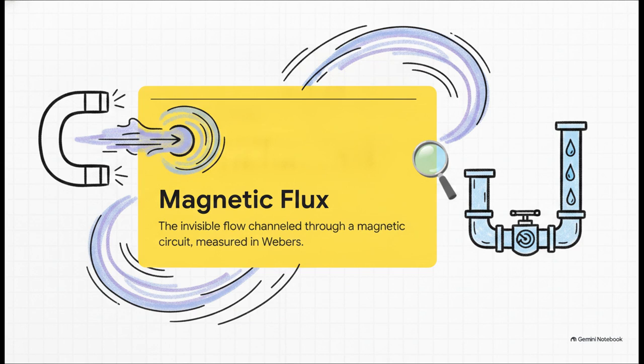Just like physical copper wires channel electricity right through your home, magnetic circuits use closed loops to channel invisible magnetic forces. And the absolute core component of this path, that's magnetic flux. It's represented by the Greek letter phi and measured in Webers. You can basically think of magnetic flux as the invisible flow being channeled through our circuit. If we use a plumbing analogy, which we're going to be doing a lot today, this flux is essentially the water flowing through the pipes.